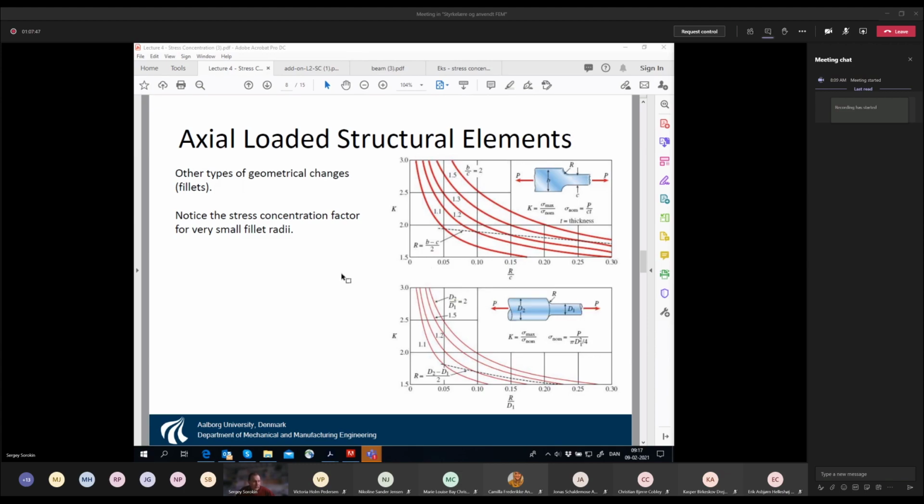But if you do the mathematical theory of elasticity, then you have what are called conformal transformations. So you have one solution, and this solution is equally valid for a very broad range of problems. So it's not that difficult. But if you do finite elements, then I'm afraid for each particular geometry and each particular material properties, you have to run your finite element code.